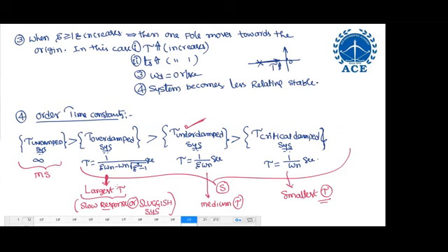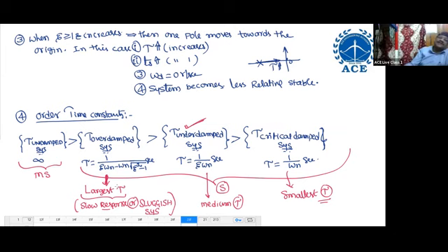Okay, sir, got it. And sir, while we were deriving for overdamped, while doing partial fractions, why didn't we consider only the dominant pole and ignore the other? We can. Just for explanation, I took both. We can take it directly only. To draw the exact response of overdamped, I considered both.